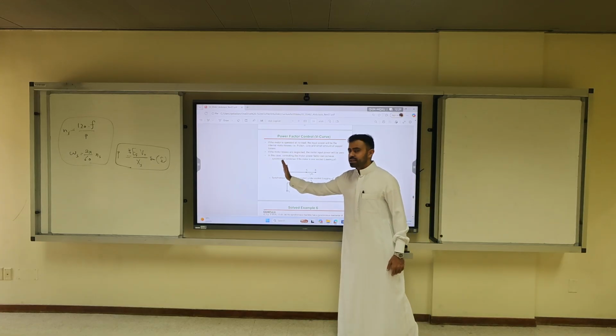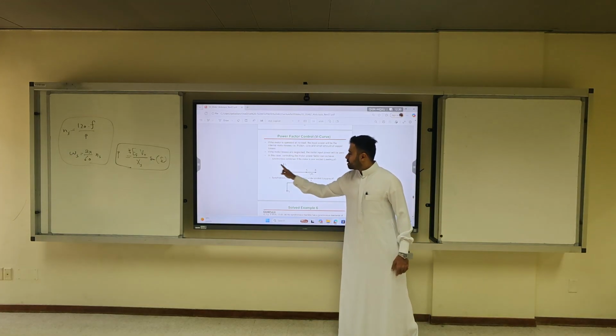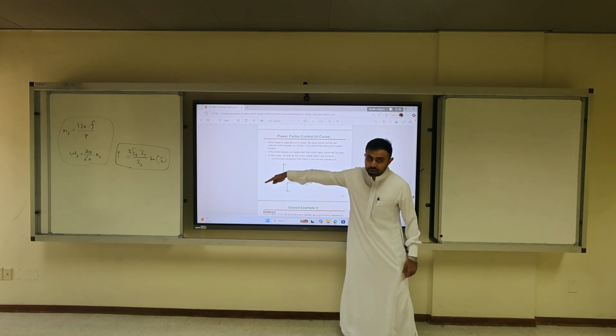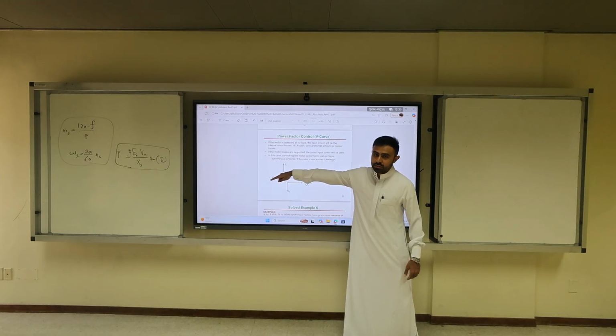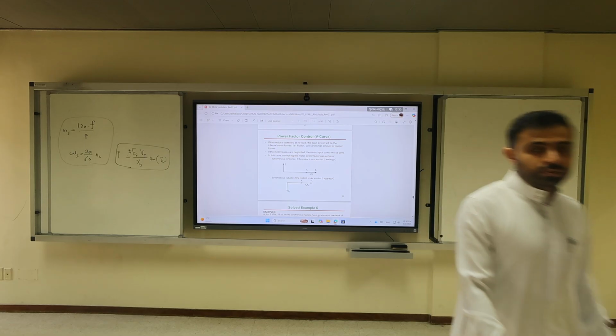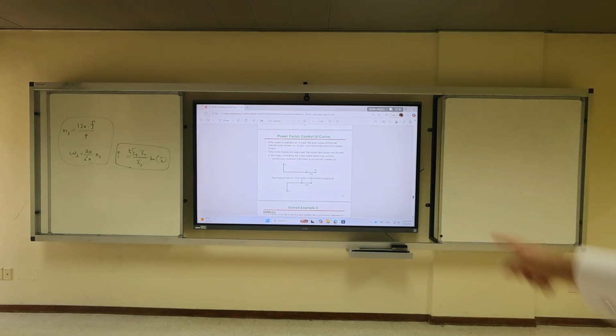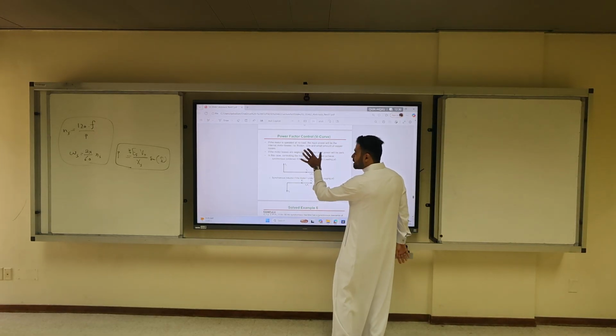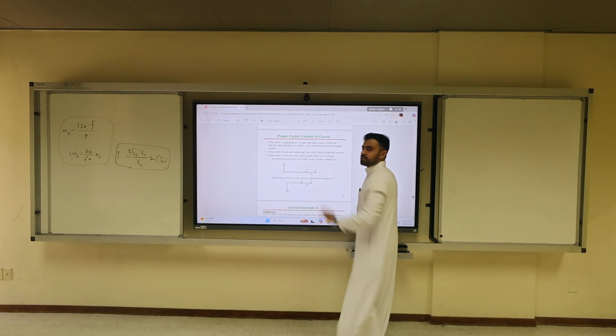If Ia is 90 degrees leading, then If will be in phase, so the torque angle is 0. What's the power factor of the motor? What is the power factor for the synchronous condenser?